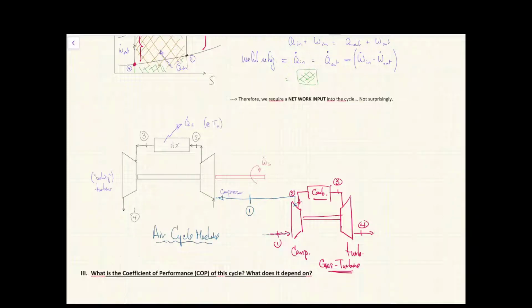Right? So very similar to the Brayton cycle, which we could run theoretically in a closed cycle fashion, but in practice we don't do this. We take air from the outside and we dump it as exhaust. Here, in the case of the reversed Brayton cycle, in a similar way, we take air from the gas turbine engine at a suitable pressure, and we dump the outlet of the expansion turbine into the cabin, and that's our cooling. That's our cooling air.